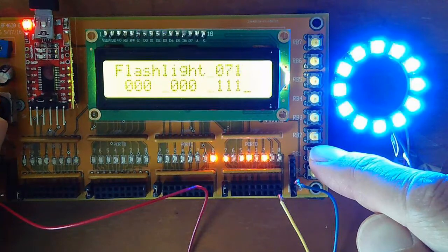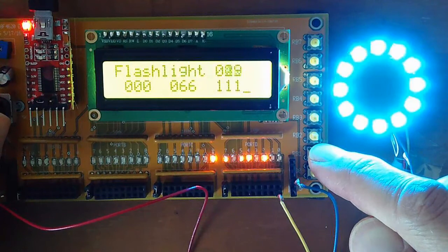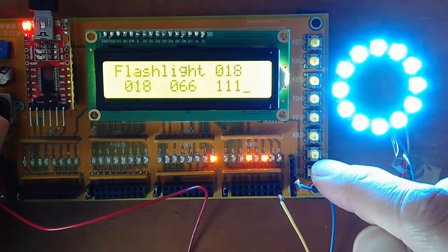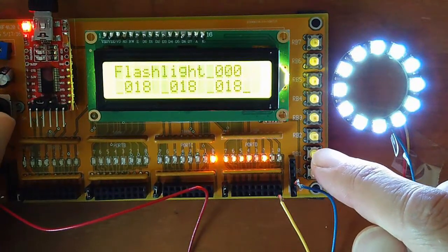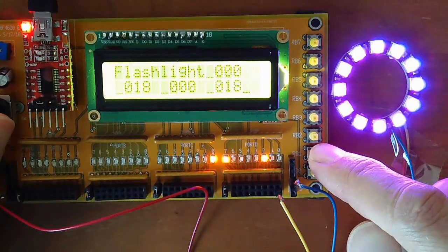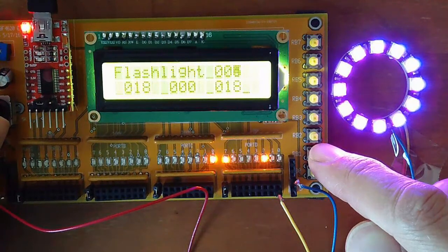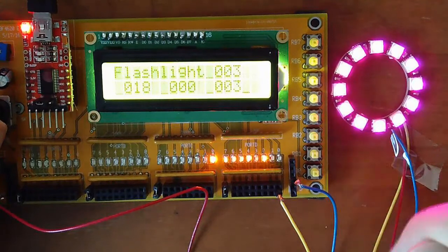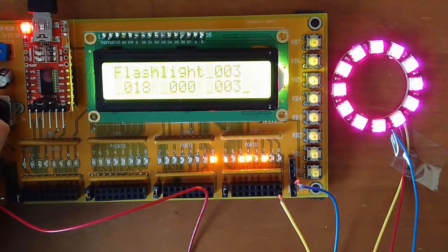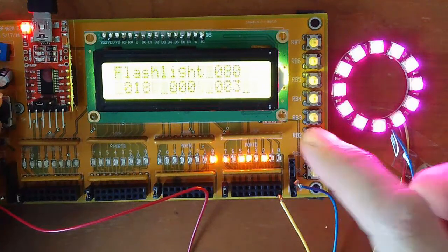If I now say, let's make the green level 71, that's kind of a teal. And let's make the red level 18. Make everybody 18, I get a white light. Get rid of green. I've got kind of a pink light. Let's make blue a little bit dimmer. Let's make blue equal to 3. That's more of a pink. I can vary the colors, or the hue, by using this as my input, 0 to 255, and setting the color.